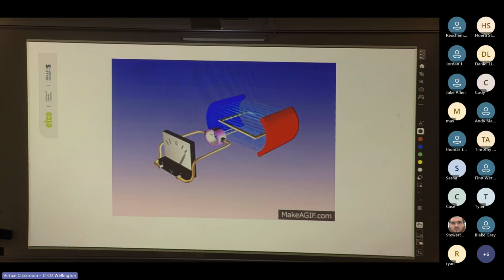As the coil rotates inside the magnetic field, those rings switch which side of the coil is connected to which conductor, so the voltage is only ever going one way. It's a form of commutator. This ensures that if we're generating DC, we only get DC instead of AC. So that is a very basic one-loop DC generator.